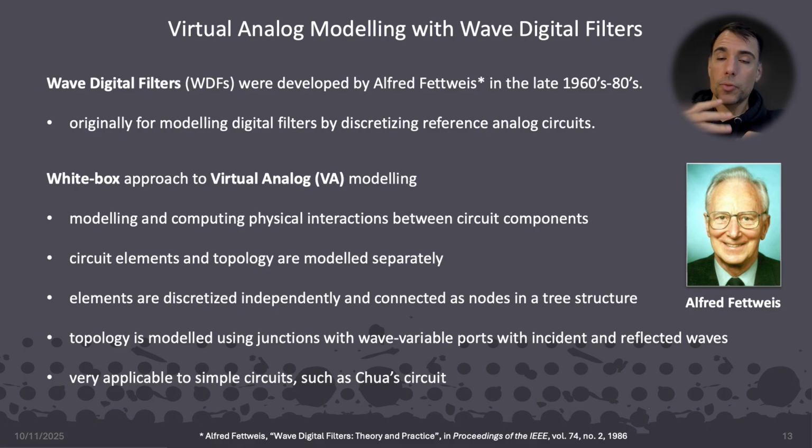So in this approach, circuit elements and topology are modeled explicitly and separately. Elements are discretized independently and connected as nodes in a tree structure, and topology is modeled using scattering junctions with wave variable ports with incident and reflected waves. So this is very applicable to simple circuits like the Chua circuit. But in the last 10 years, research has developed this approach and made it more generalizable and powerful.